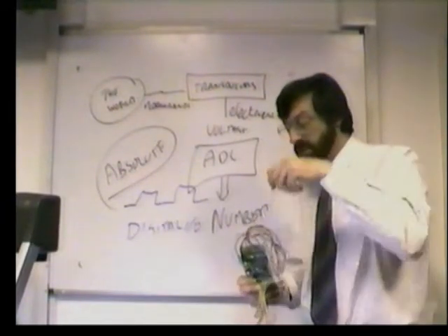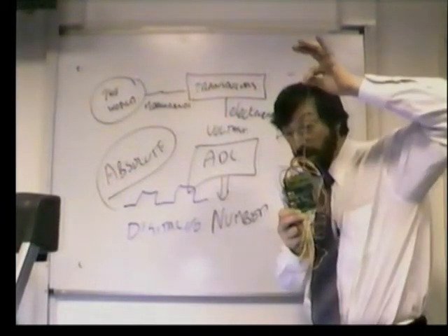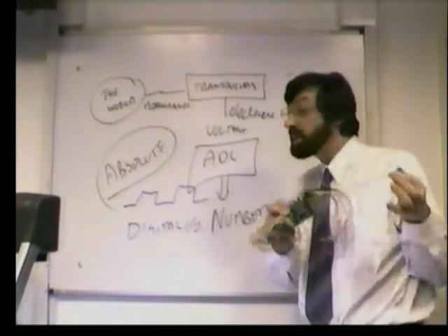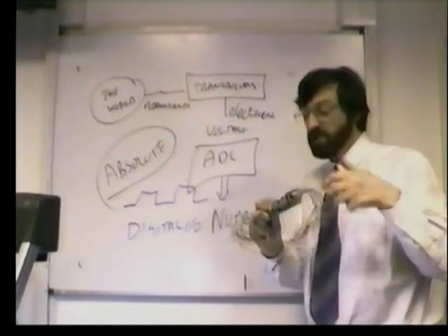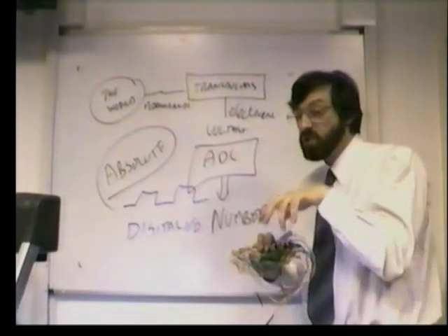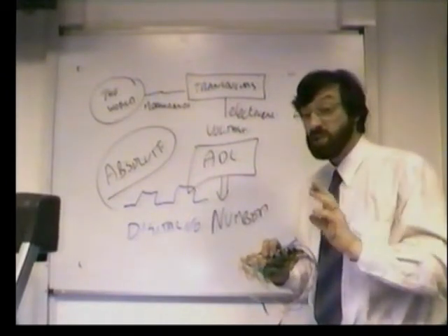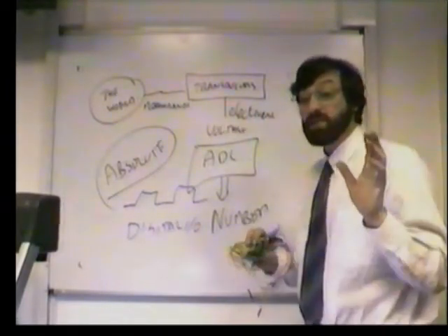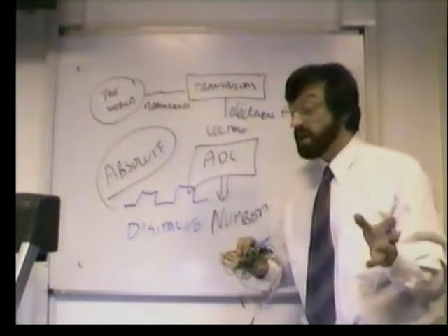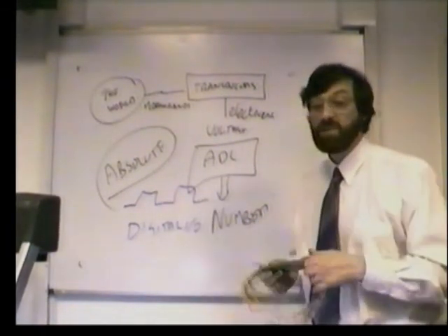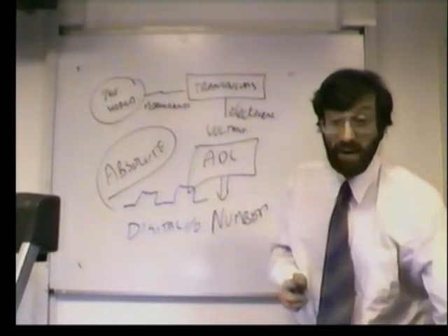So you can write a program that accesses these directly. So you can say, right, what is the state of that wire? Is it a 1 or is it a 0? Remember, computers are stupid, so they only know binary, a 1 or a 0. And that is how you read in digital data. And if you've got a timer as well, which is essential, some form of independent real-time clock, and we'll look at those later, then you can time the rate of arrival of these pulses, and that gives you frequency information.